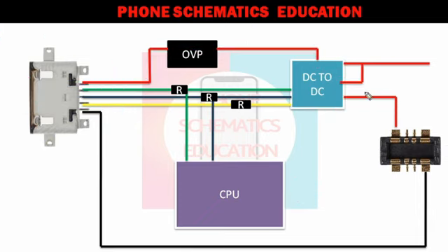I'm telling you again. When you connect the OTG, the requirement is near about 5 volt. Right? Now the OTG is connected, and your phone runs in battery mode. So there is a MOSFET reverse working. Your phone runs on the battery. Now, the same voltage through a MOSFET goes back to the V bus line. How?